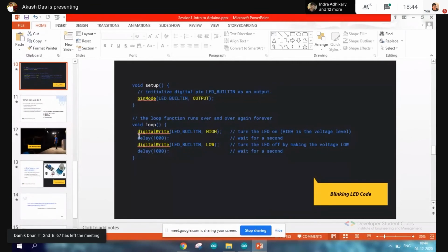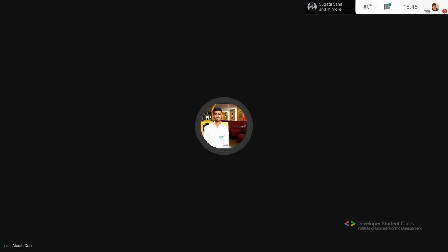If you use delay in your program, it will stop the whole microcontroller processing and do this thing only. So this is very bad for execution when you are working on multitasking work. Can you think of doing it without using delay? I'll tell you about this after I show this.